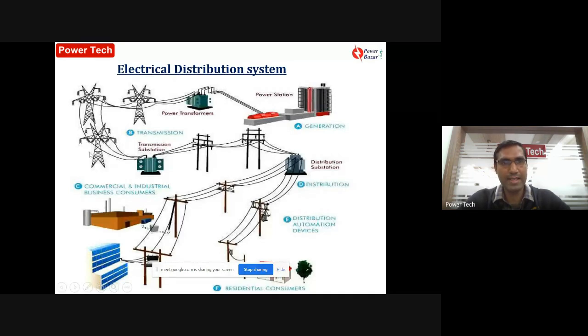Once it is transferred, it comes to the transmission substation where it is stepped down to a lower voltage, to 33 kV. Then from 33 kV it is stepped down to 11 kV. If a consumer is at 33 kV, that would be a 33 kV primary consumer. When it is stepped down to 11 kV, we have 11 kV feeders. From the 11 kV feeders, it reaches our locality for local distribution. There it is stepped down to 415 volt, and from there it can be given to distribution consumers.